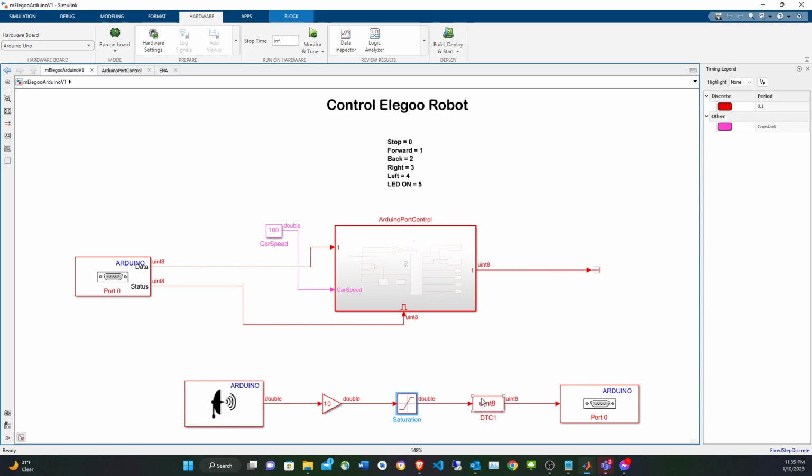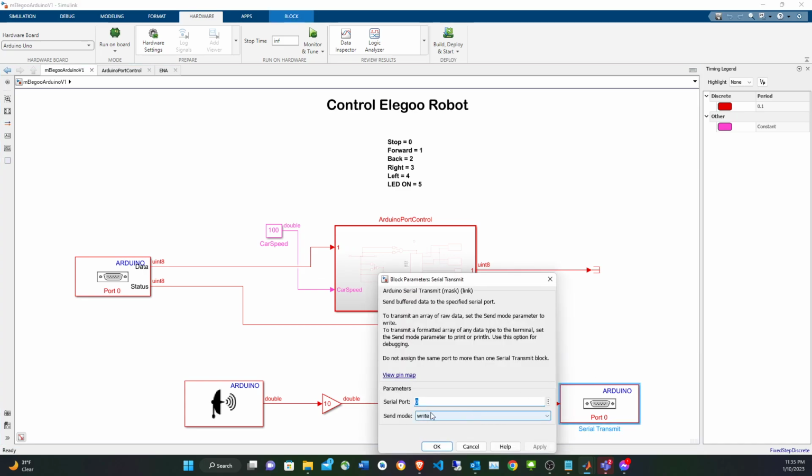I learned this, I had some time debugging this, but then I realized that I had to have the same type, so you can fall into the same issue. So be careful with the data types. So then I communicate the distance, the ultrasonic distance, through the serial transmit. It's going to be a send mode, right, Arduino general transmit serial.